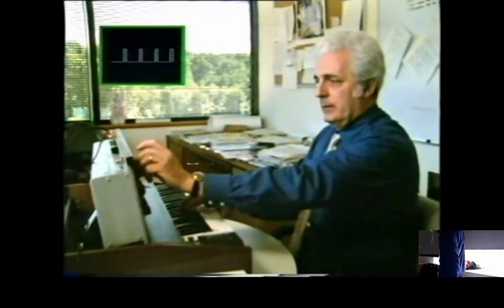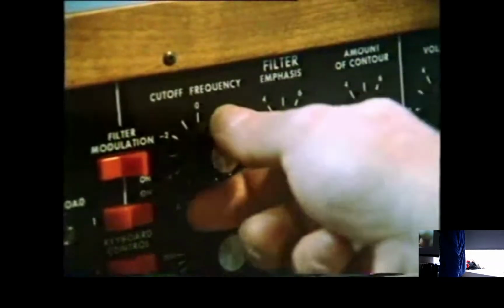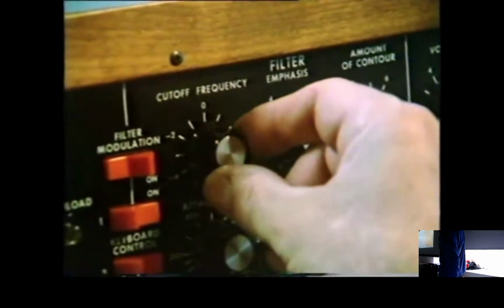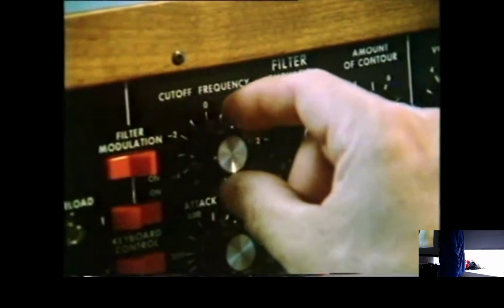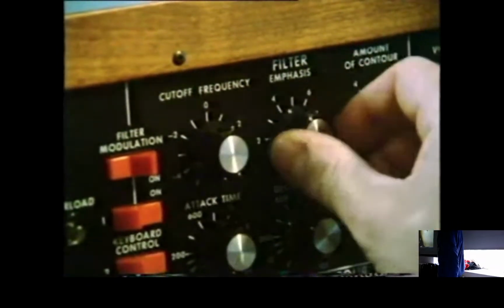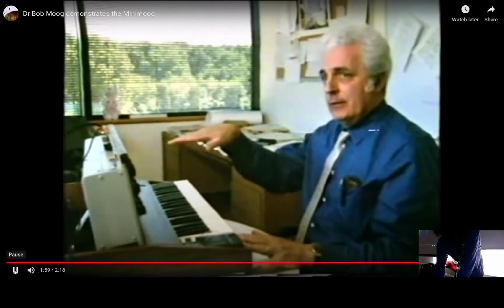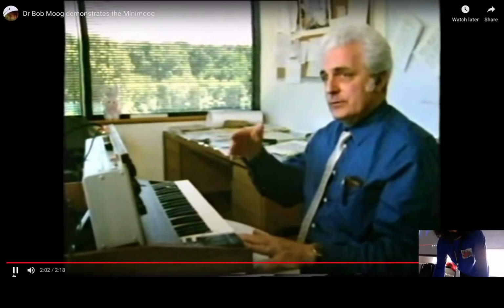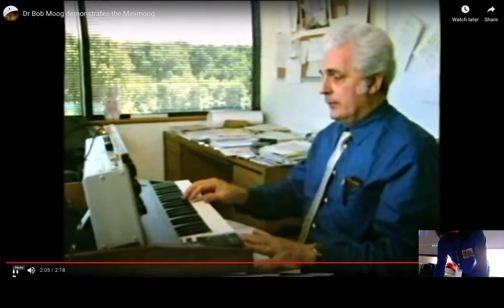With all those harmonics, we can shape the sound through filtering. That is, we can cut out these harmonics as the sound goes on. Here's a filter which cuts out the harmonics starting with the highest. Another important aspect of the sound is its envelope, how it builds up and decays as it goes on. In an analog synthesizer like this, there are 4 parts to the envelope. The attack, which is the rise, the decay, which is the fall from the highest point, the sustain, which is how loud it is as it continues, and then the release, which is how rapidly it dies to zero when you let go of the key.